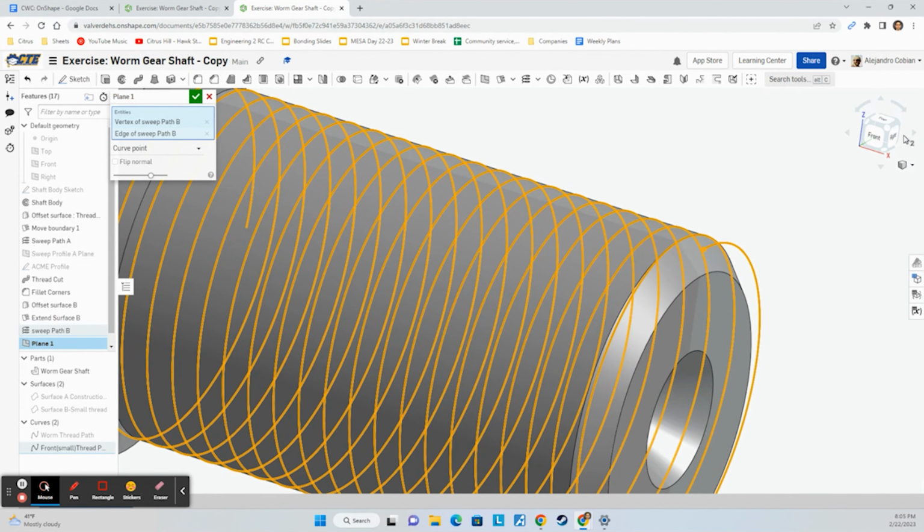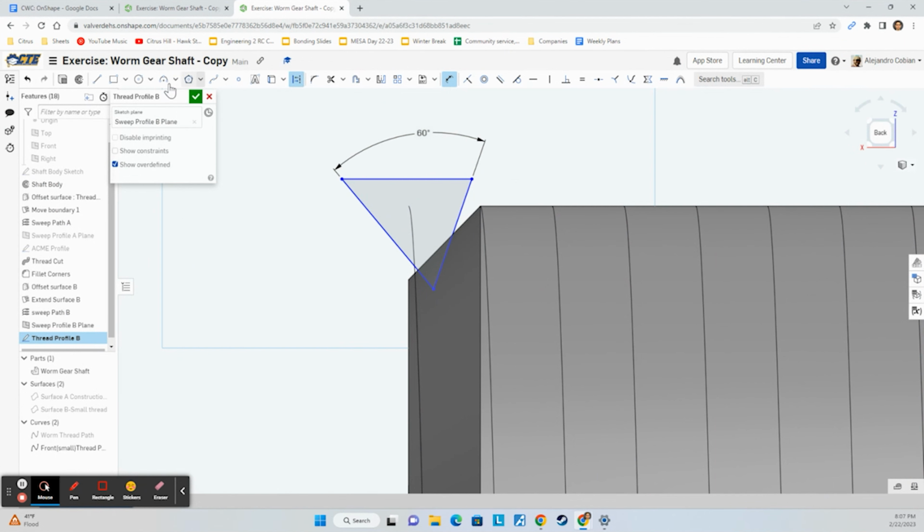All right, so now let's add our dimensions. So we have the letter D. So we're in dimension. Our angle between these two lines will be 60. And let's actually add a construction line. So hit this and this line. And let's find the midpoint here. And let's connect it to this point there.